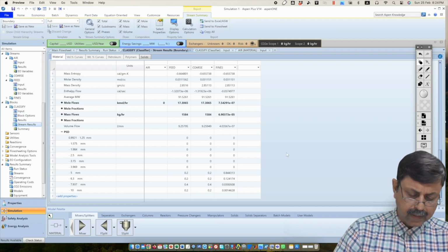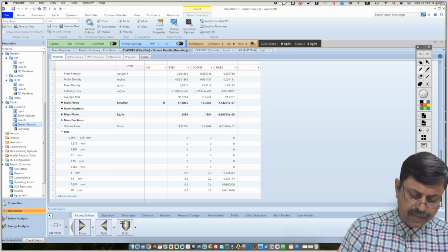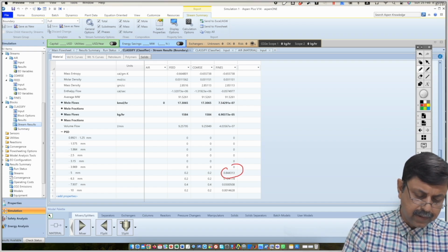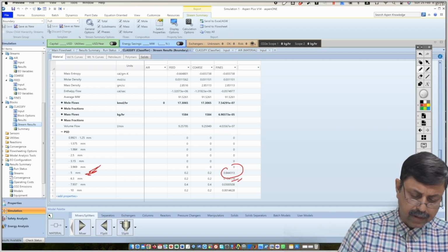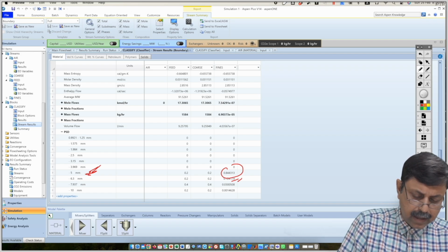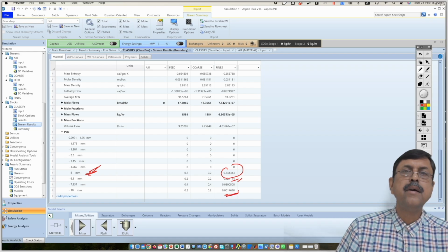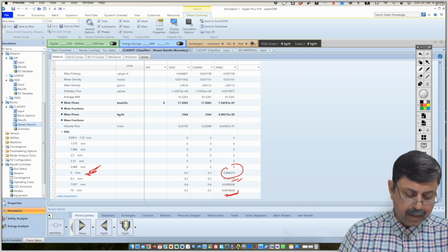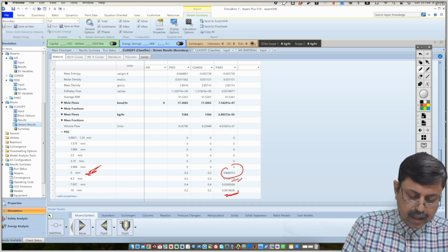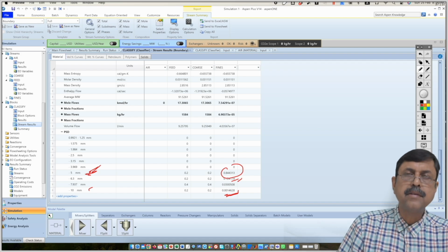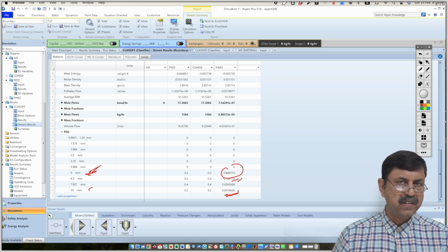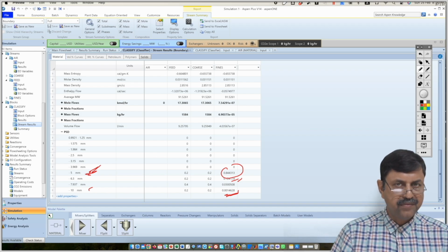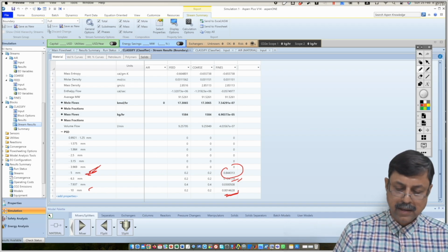Okay, so this is somewhat good. You can see in the fines material, 84% of the fines material is there in the 5 millimeter range and 0.12% over here, and in the 10 millimeter range a very small amount is there. Only 3% is in the 8 millimeter range. So by using a 3.5 meter by 1.5 meter Sifter, we have achieved a somewhat better result.